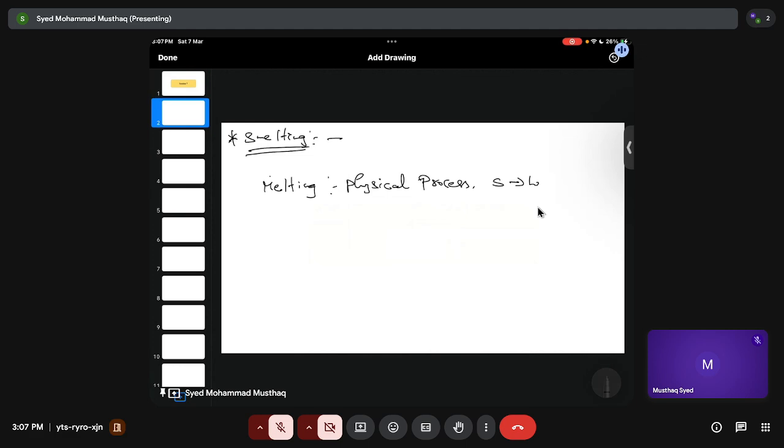Now smelting, whereas, may involve a few chemical reactions. So it is also a conversion process. It is a part of pyrometallurgical process, because we are supplying heat energy. So it is a unit process, not a unit operation. Unit operations are mostly what you do before, like comminution, flotation, or the few types of enrichment process that you do. That is the unit operation. Now we are talking about a unit process.